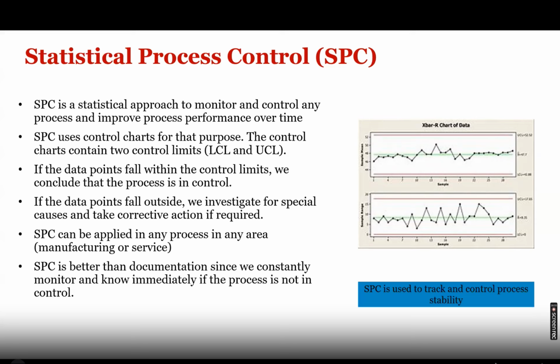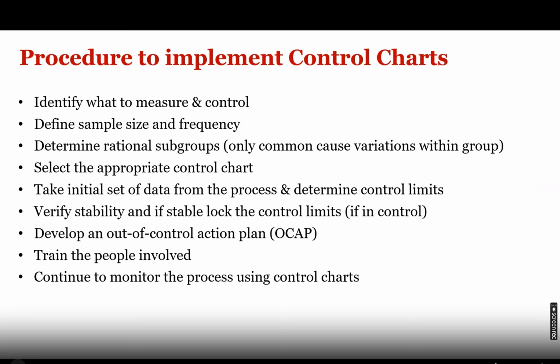So with the improved data, if you plot control charts, it will plot your control limits, which come out of the improved data itself. It shows that ideally your data will always reside within the control limits. It should not go above the UCL or fall below the LCL, which indicates that your process after improvement is well under control.